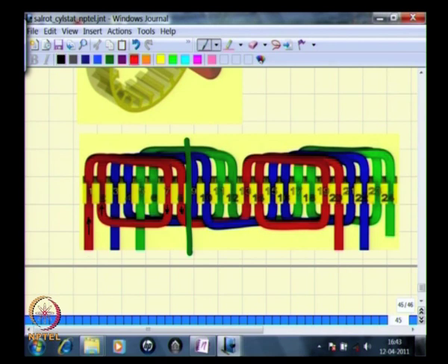The nature of the MMF then, since currents are flowing in here, you have a variation, assuming that the slotting is not there and whatever is spread uniformly. This we have discussed earlier. The MMF distribution may be drawn as a straight line till this point, and then it remains constant until you reach here, and now the currents are flowing in the opposite direction, so it decreases linearly and then it remains constant over this region and so on.